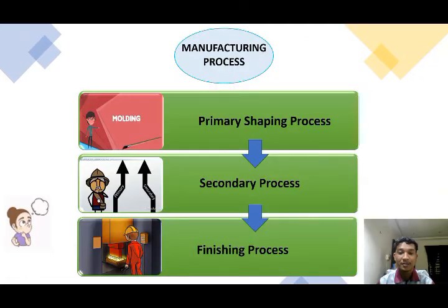Hello doctor, my name is Muhammad Farid and I will explain the manufacturing process for the earplug. For the primary shaping process, the mold includes a first cavity that limits expansion of the outer layer, and a second cavity in the form of a stem portion. The first cavity is oriented below the second cavity. Next, the outer layer is thermally bonded to the elongate core.